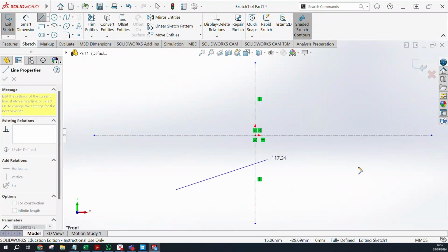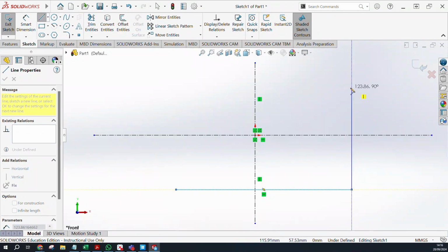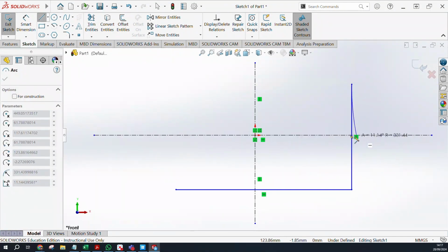When you are drawing something and it reaches a proper parallel or horizontal axis, it will show you this sign, the yellow sign. You can see it shows that you are now on the x-axis. So you need to click again. It will now fix it, and then it will start a new direction. When you go up, it will show you the perpendicular or y-axis constraint. It is called a constraint. Now this constraint is green, like it is fixed now, and it is defined that this line is perpendicular or on the y-axis. So sorry, I selected another command.